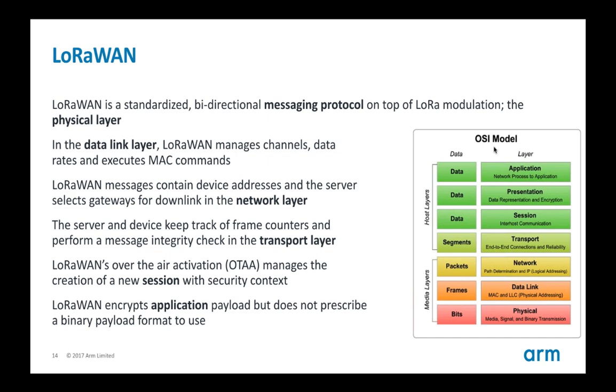And finally, the application layer is also partially affected by LoRaWAN, because there is encryption of the application payload. So there are basically two session keys. One is for the network and one is for the application. And LoRaWAN does not prescribe a binary payload format to use. So you can use any encoding on top of LoRaWAN for your application.